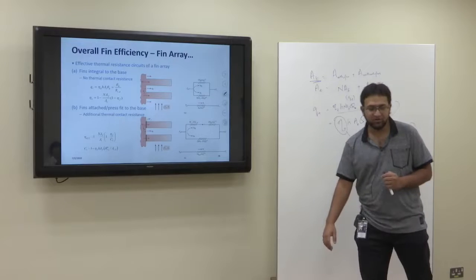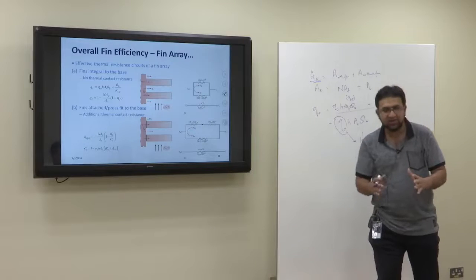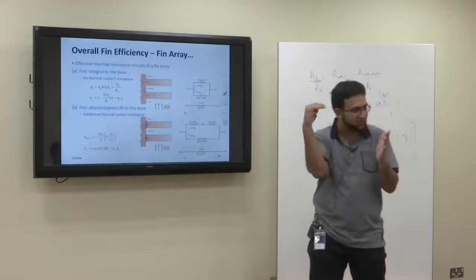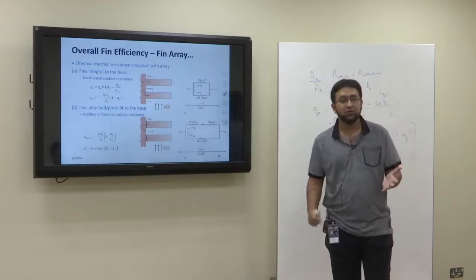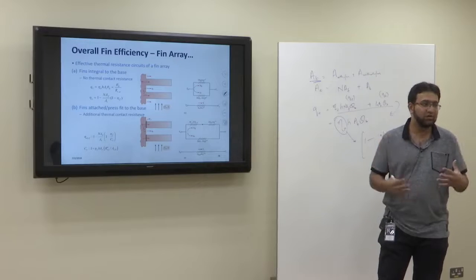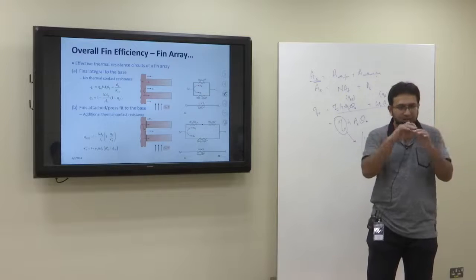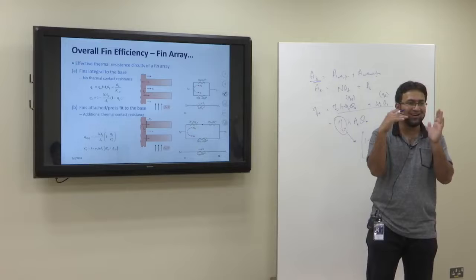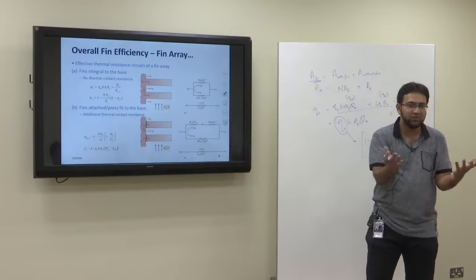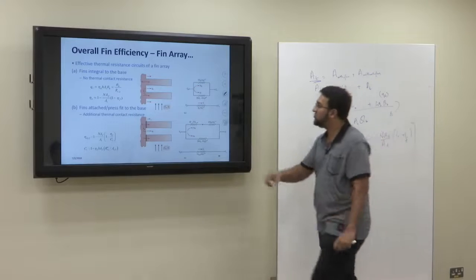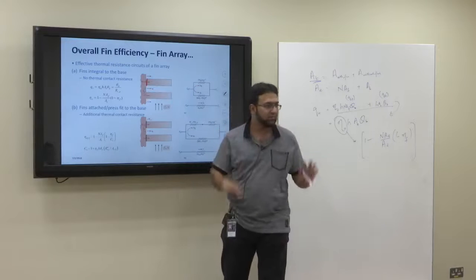Now there is one more thing added into it here. Look, you have the main body and then you attach an extended surface to it. Sometimes it is attached in the designing phase. So when you are designing that device, you already know that you want to add the fin. So in the casting process, you made a provision for the fins, and the fins are integrally joined in it. So they are not separately joined. They are a part of the main body. So there is no joint here.